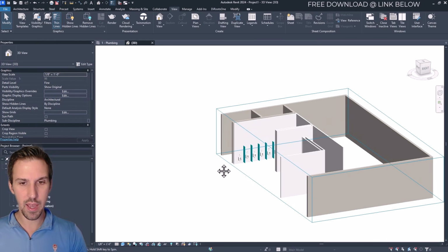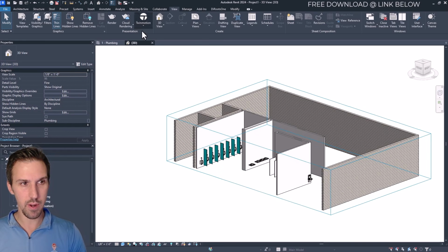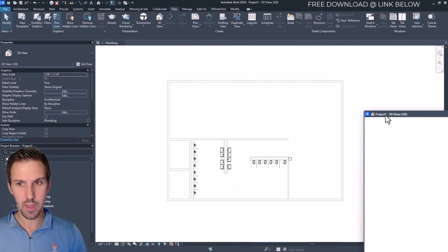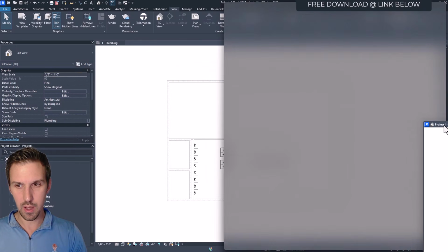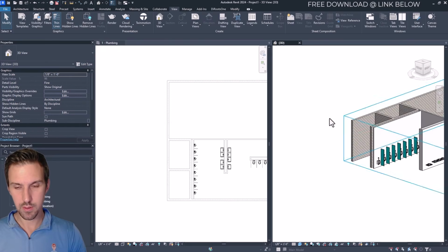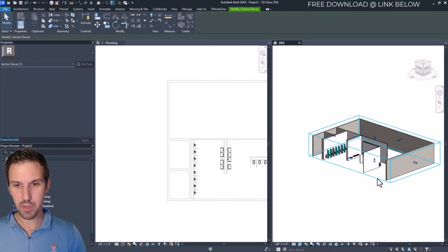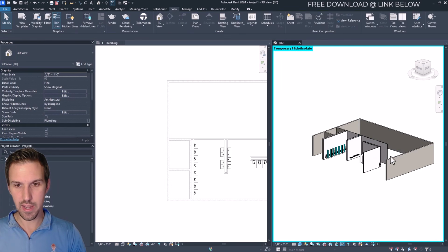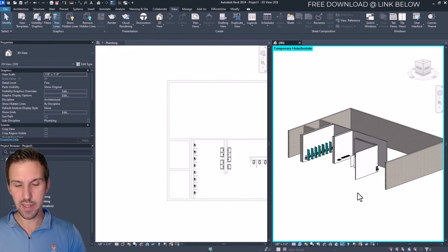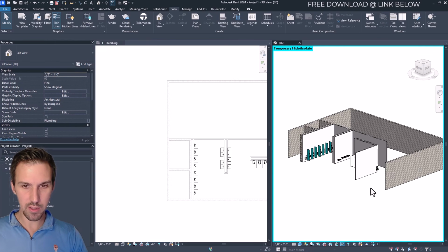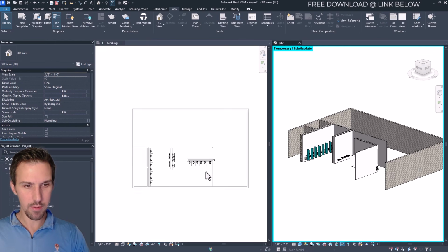So I'm going to move my 3D view over to the right side of the screen by dragging it over. And we're going to drag it into where the little scroll space is, just like that. And if we want to temporarily hide this section box, we can. We can just click the little sunglasses down here and hit Hide Element, and it's just hiding that temporarily. So that looks great. Now let's look back on our floor plan.